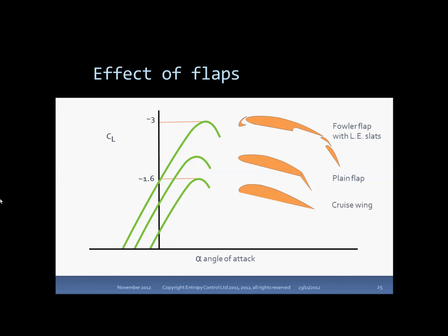Once you get to larger commercial aircraft, complex slotted Fowler flaps together with the leading edge slats really do pretty well double the maximum lift coefficient to 3 or more. But the effect is not purely aerodynamic. When the flaps and slats deploy, the wing area increases substantially, so part of that high lift is simply due to a bigger wing. That concludes the section on lift.